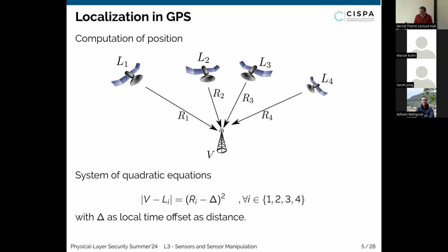The alternative to just stupid jamming would be that the attacker is actually adding their own signals that either try to confuse your receiver quite a bit, by sending a very strong signal for satellite 1 with a completely different pseudo range, and then your receiver might be confused about its own location.